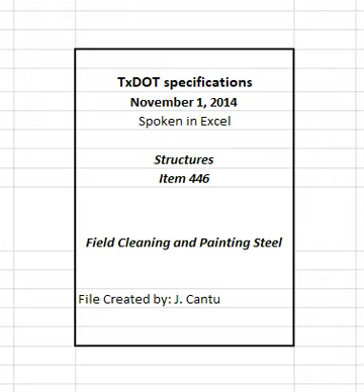4.7.3.2 Classes of cleaning. The requirements of Section 446.4.7.3.1, General Preparation, apply whether or not a class of cleaning is specified. Use an approved abrasive for abrasive blasting. Do not use steel shot.